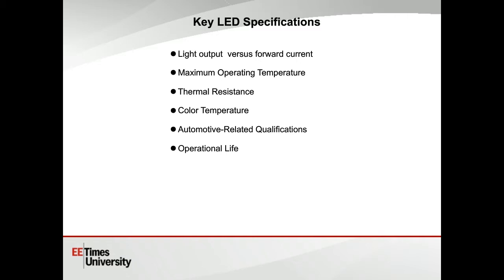Thermal resistance is another key specification, not only for LEDs, but for pretty much any power semiconductor. This is defined as the rise in temperature of a component per unit of power dissipated. Typically, it's expressed in degrees C per watt.